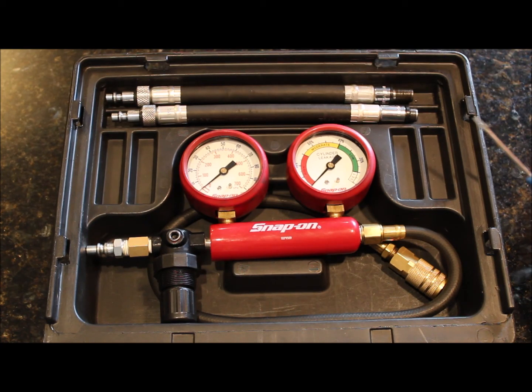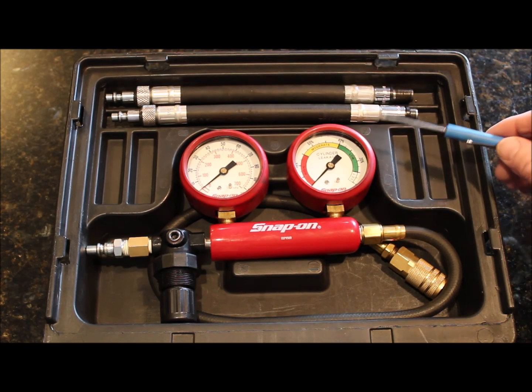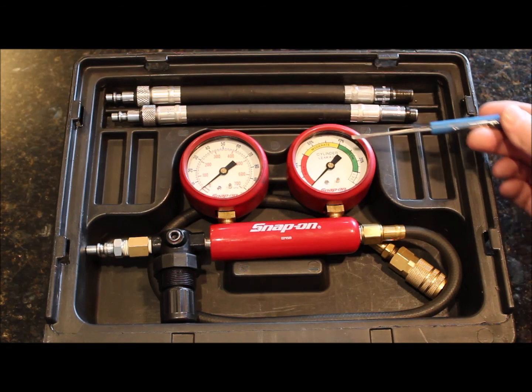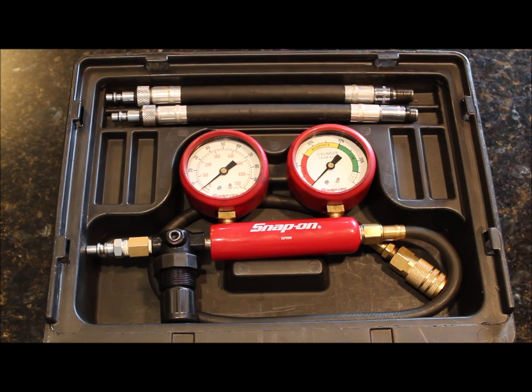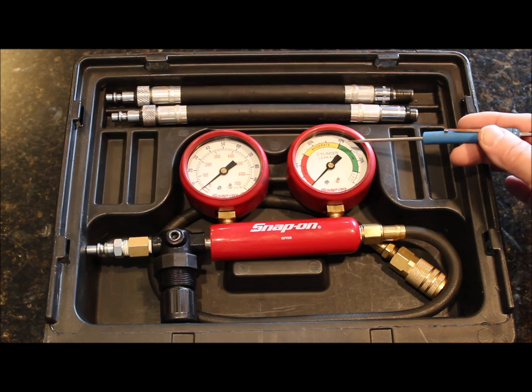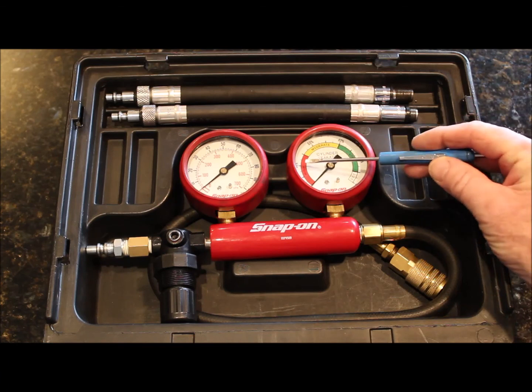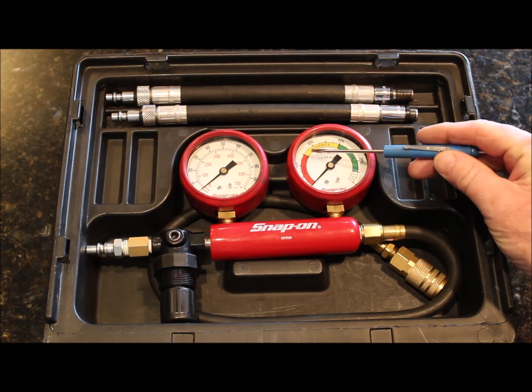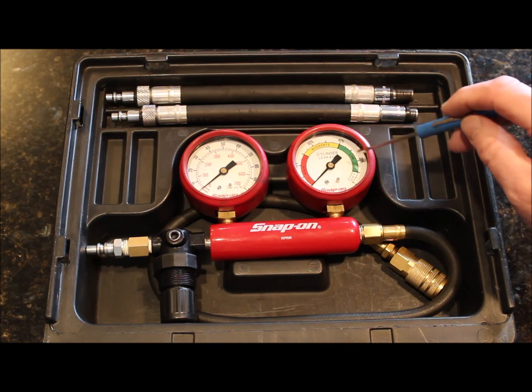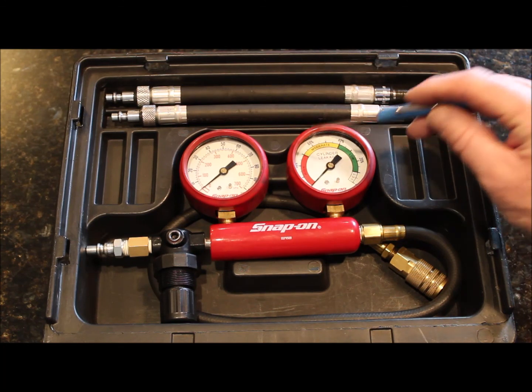I've always been told that up to 10% leakage is absolutely normal. The green, yellow, and red on this gauge are a little bit different. It has almost up to 40% in the green saying it's low, and then from 40 to about 70% says moderate, and anything over that is listed as high over here. So right here, this is 20, this is 40, 60.